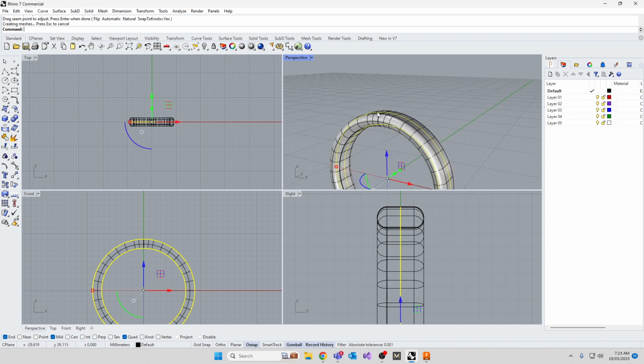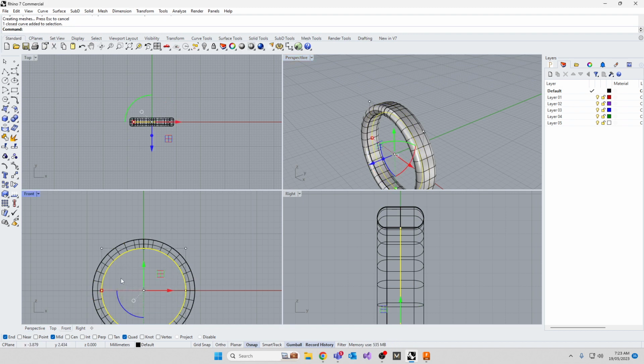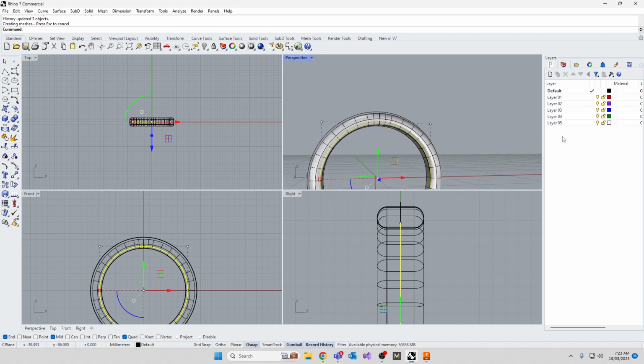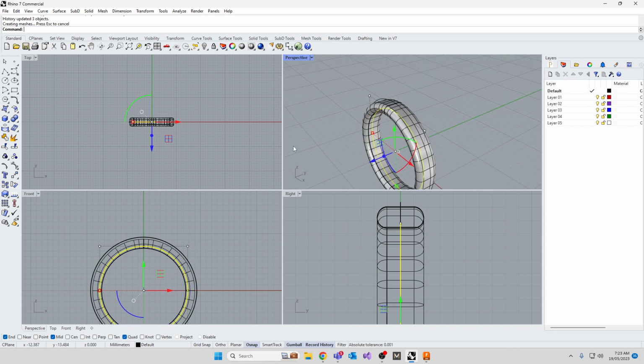So you've now got the fillet, and hopefully if you change that inside curve, you've still got the history for the offset, which means... no, it didn't. Even though it didn't tell you it broke history, it broke history. Yes, I get it. So that's the downside to Rhino. However, in solid modelers, doing something like this,